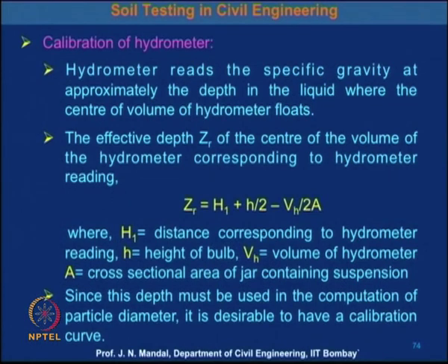Now, we require calibration of the hydrometer. This is important, so how can you calibrate the hydrometer? The hydrometer reads the specific gravity at approximately the depth in the liquid where the center of the volume of the hydrometer floats.